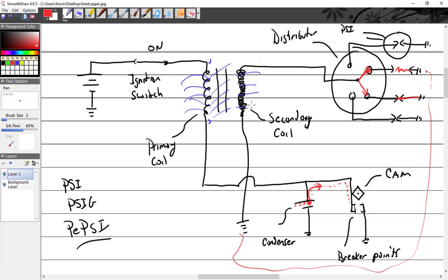So you need the high voltage to pass this gap. Yes. If the secondary makes a low voltage, it won't pass this gap. So let's say we had a short somewhere, and half of the secondary voltage is not working. It's supposed to give me 20,000 volts, but half of it's shorted out, so the best I can get is 10,000 volts, and that's not enough to jump the gap. Then you've got nothing. It's not going to work.